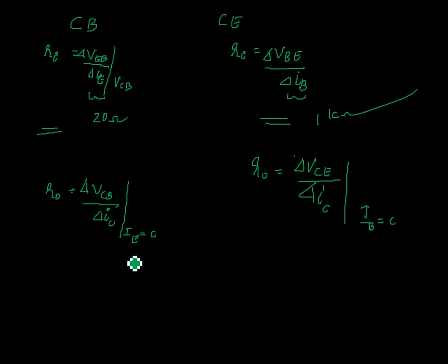So in this case, you know that the output characteristics of a common base configuration, if you observe, are almost horizontal. IC is equal to IE, it is following IE, and it is almost horizontal. Whereas here, for common emitter configuration, it is increasing with VCE. It is not a horizontal line there.